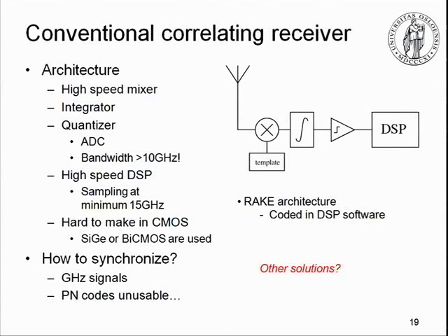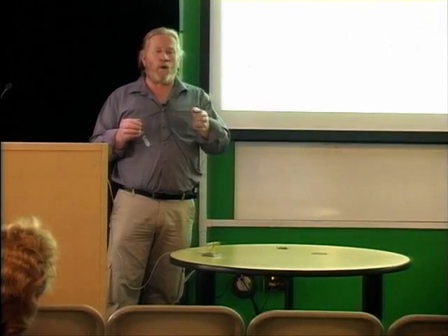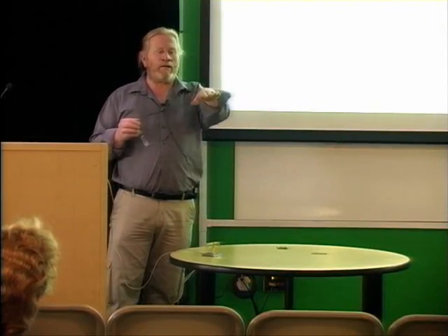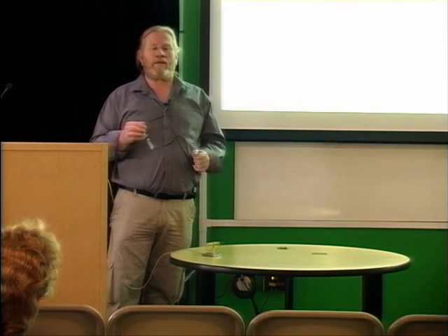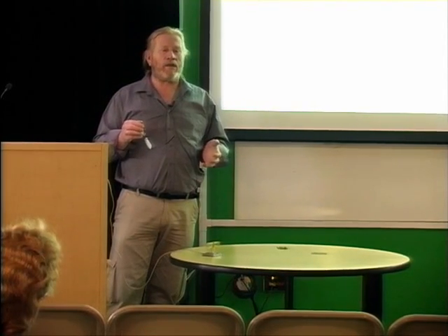So that's one synchronization problem. The other one is the sampling problem. If I really want to read the analog value of this signal, I have to sample at a really high rate. So our solution is using a binary value: just a very coarse binary sampler, put a threshold and check if my signal is below or above that threshold. That's a very coarse quantizer, and that's something which is feasible. If you want to do more bits, it's really hard. So I'll try to present you a continuous time binary value solution.